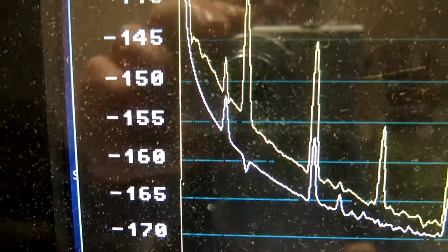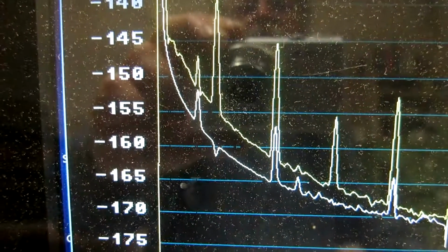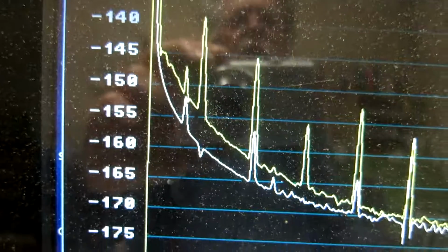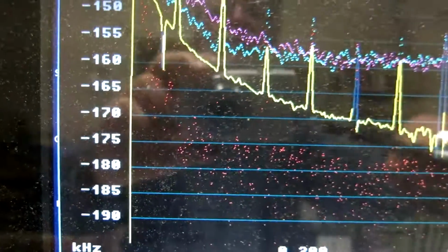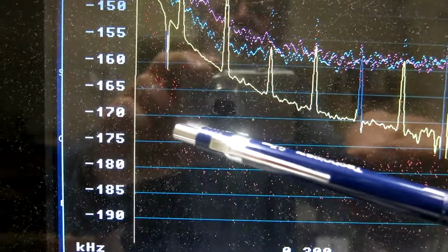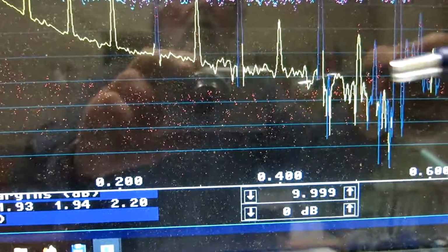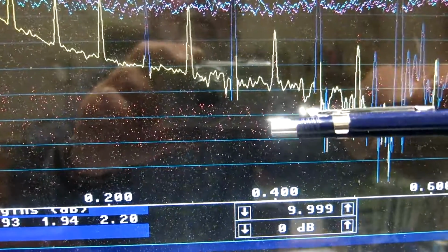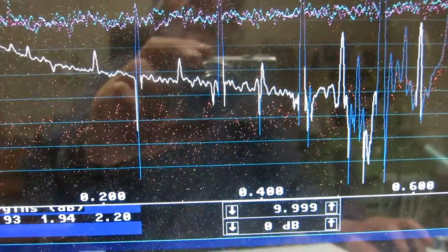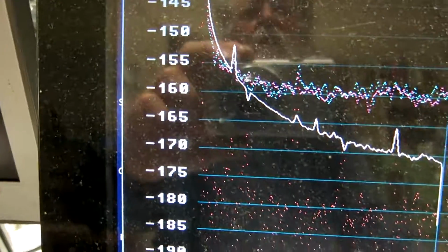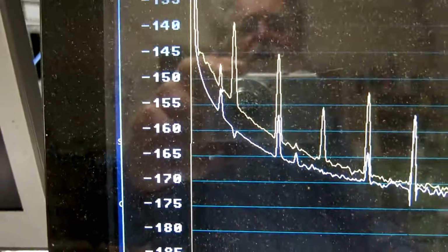The upper trace is the yellow, which is phase noise. So the amplitude noise is at minus 160 at 50 Hz. And I click to the other screens. Here we can see that phase noise, the imaginary part, is down at minus 175, so it doesn't contribute. And all the way up to 400 Hz, I have waited long enough. And for the AM noise it looks similar, and also here. So I can use these curves to evaluate and write in my table.